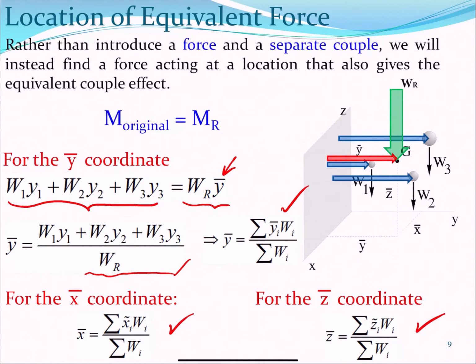Now, the direction of the gravity didn't matter. The direction that these particles are being pulled won't matter. If we have the gravity acting on the z-axis or the x-axis or along the y-axis, the position of x bar, y bar, and z bar, the position of the resultant force won't change. We'll just have the resultant force passing through the same point and being pulled in whatever direction the gravity is acting. So it's independent of the direction of the gravity force.